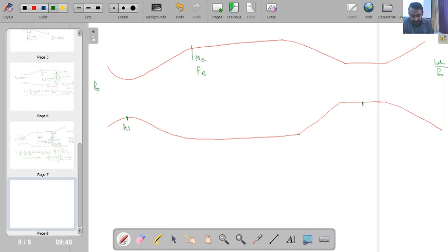Say this is my A1 and this is A2. What I can say is that I have a nozzle which starts at 1 atmospheric pressure condition, gives me Mach number equal to 1 at the throat, then results in isentropic supersonic flow, then gives me the required Mach number at the exit, some pressure at the exit.